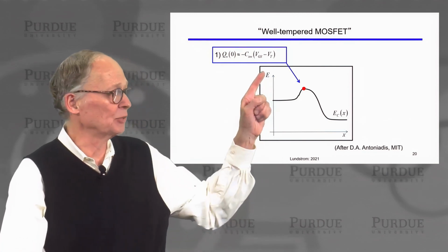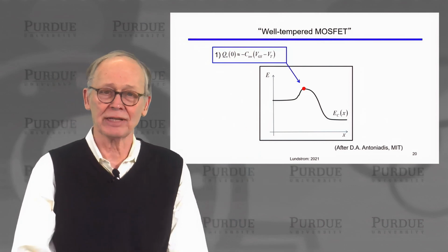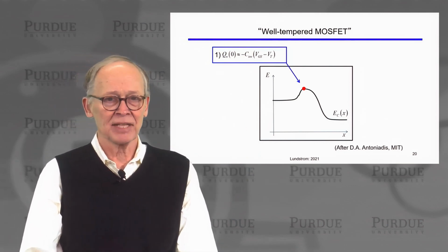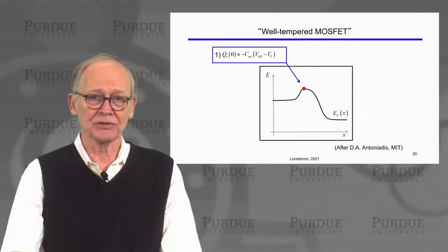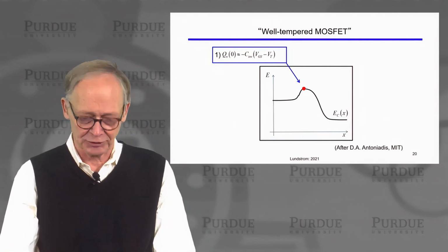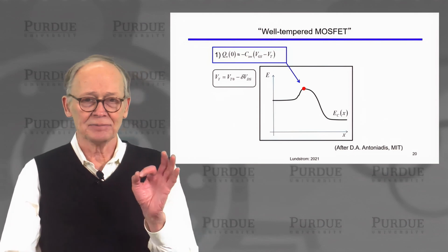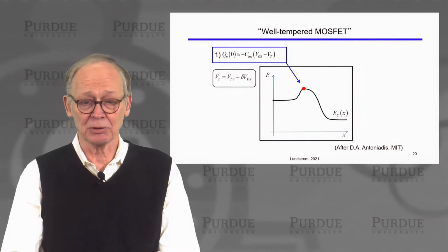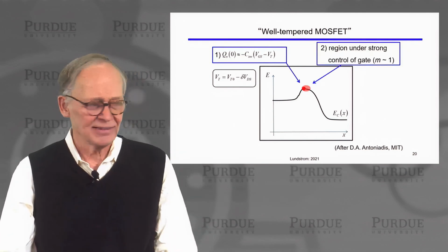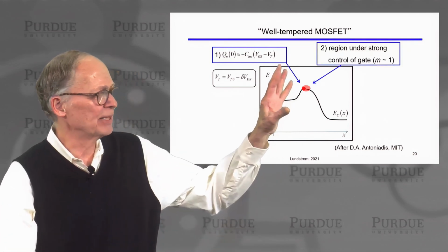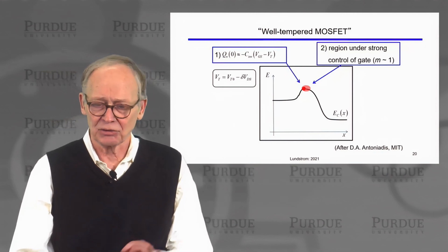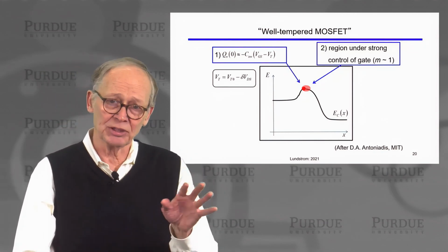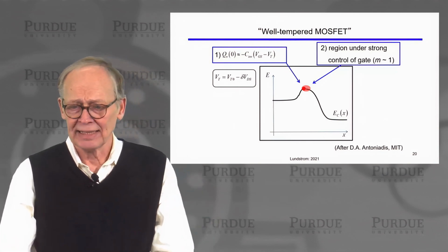It's a MOSFET in which the charge at the virtual source, or at the top of the barrier, has this very simple relation that would apply in a long channel device or in a one-dimensional MOS capacitor. We have a small correction due to two-dimensional electrostatics through the DIBL parameter delta. There is a region near the beginning of the channel where the slope is very shallow. The curvature of the band is very weak so that the one-dimensional electrostatics works.